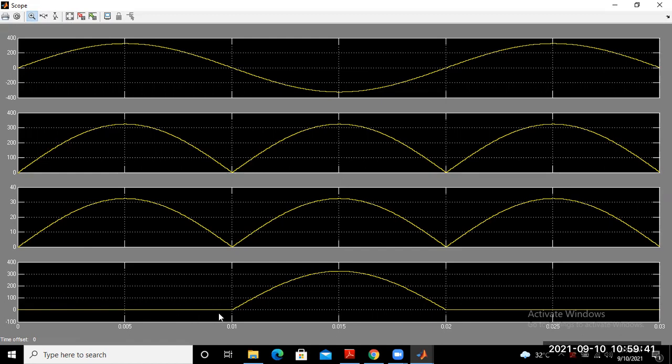And in the negative half cycle, you have to obtain the negative waveform. But again it will show the reverse polarity, so we have to connect another voltmeter across the diode.